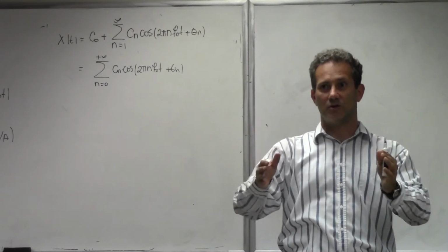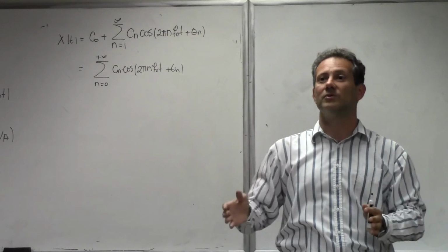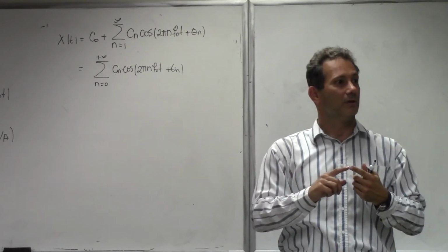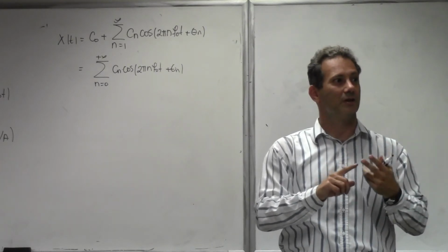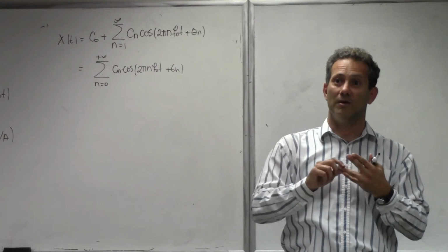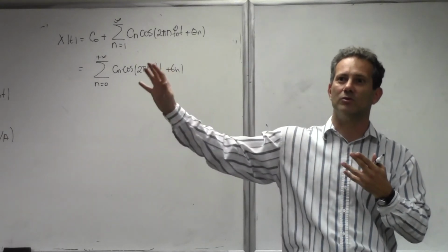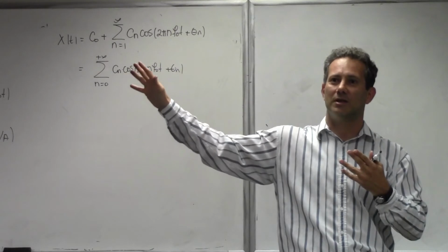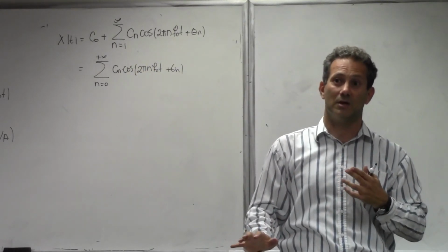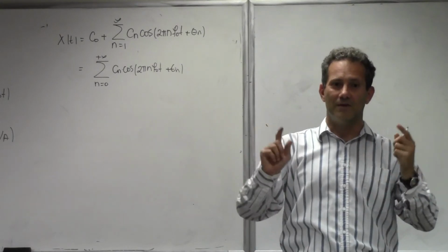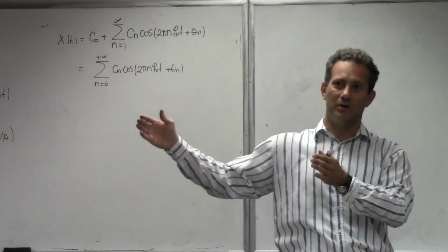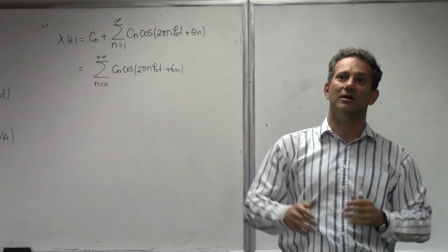When I present the sinusoidal to my linear system, what happens to the sinusoidal? Magnitude may change, phase may change, frequency cannot change. So my linear system will never produce additional harmonics. Therefore, there cannot be any harmonic distortion when it comes to linear systems. The truth of the matter is, every system is linear to a certain extent. And then through harmonic distortion, we discuss how linear the system is.